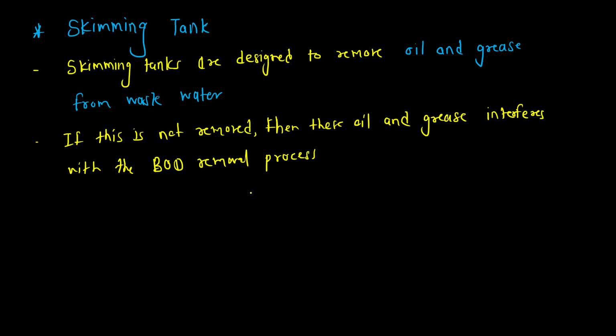So it will interfere with the BOD removal process. So we all know that specific gravity of oil, or let's say specific gravity of grease, is less than specific gravity of water. So as it is less than water, they will not settle, or they will not get sediment inside the water. Hence they will not settle in water.